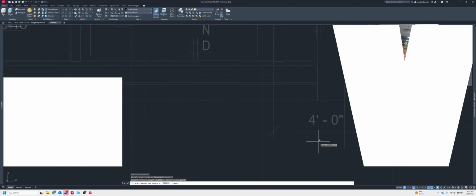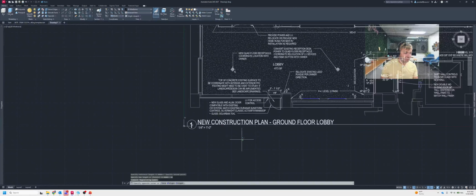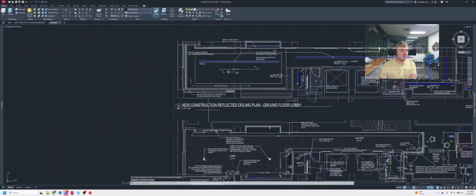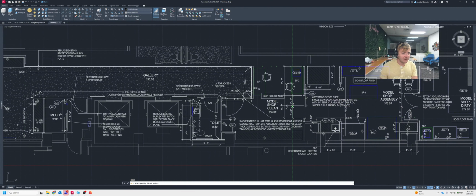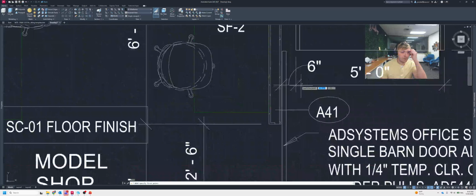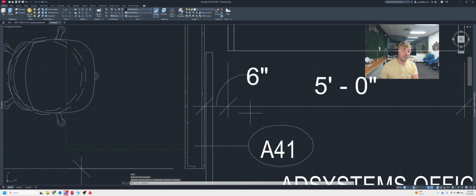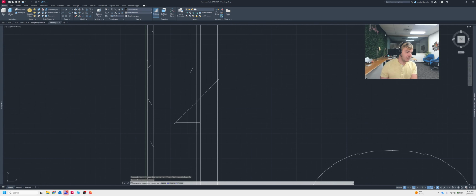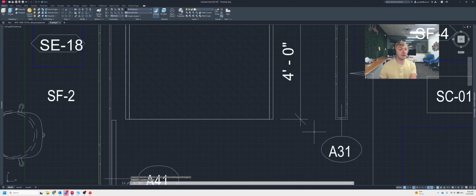So after I've selected those 2 points, at the bottom of my screen it says specify a new length between, which is 48. It's going to make this uber big. That's okay. But what I would suggest you do before you move on and delete the dimensions is just check to make sure that the dimensions do work. So like here, I'm at 6 exactly, which is what should be the case. So now that I've checked that, I've double checked my work. Let's go ahead and delete these dimensions now and get them out of here.